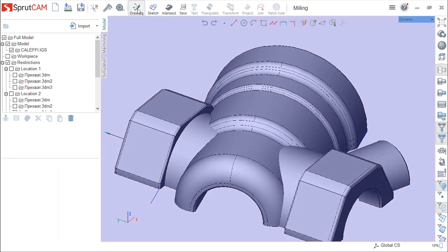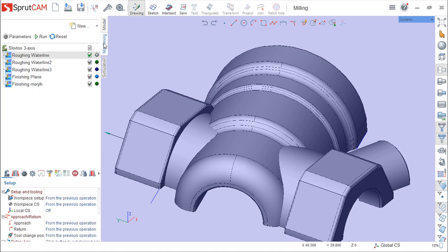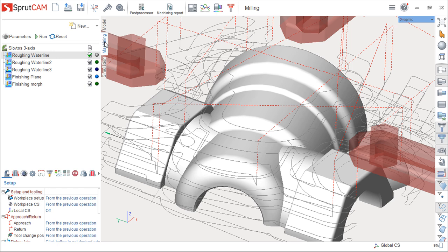But for example, to draw, we get this slightly different look, and we have on top of the screen these 2D functions which allow us to make drawings. I'm doing this randomly, but we can control what we are doing. Okay. So basically this is another improvement because this is parametric, and it also allows us some nice possibilities to create these entities that will help us in the machining.